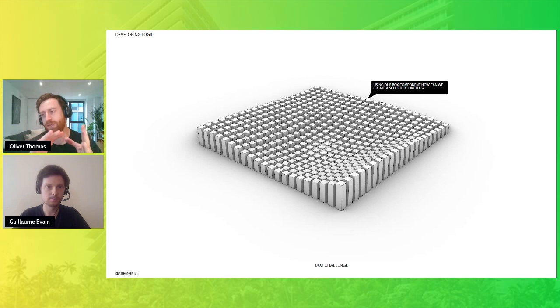From this image, I want you guys to think in your head, how would you actually make this? What are the steps? Some of you are already going to say point attractor, which is great, but start to think initially, what are the kind of things to do? One way that I would do it is I would take a box and array that box 20 by 20, and then I would use a point attractor in the middle, like you guys are saying, to change the heights of the boxes.